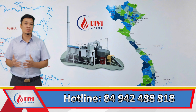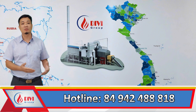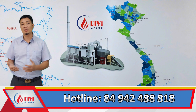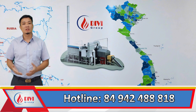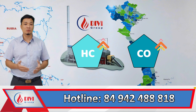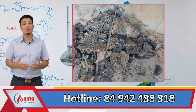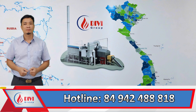Additionally, at low loads, the primary air supply is reduced and the fan pressure may be too low to keep the fluidized bed material fluidized. This creates defluidized zones where no air passes through, leading to higher emissions of carbon monoxide, CO, and unburned hydrocarbons, HC, as well as localized clinker buildup caused by uneven combustion. This represents another major drawback of fluidized bed boilers with a fluidized bed material.